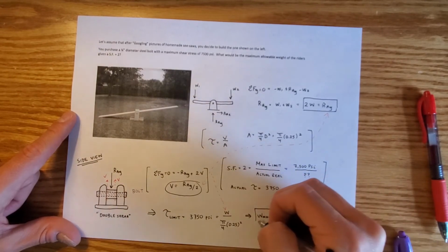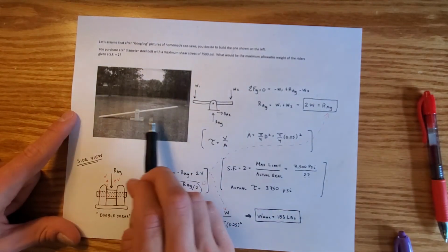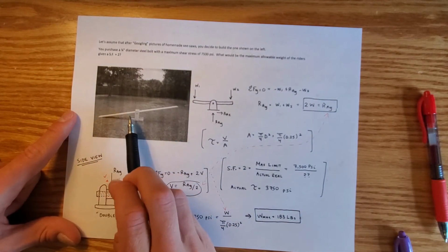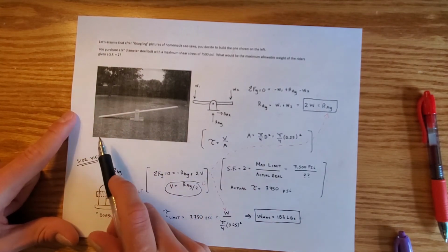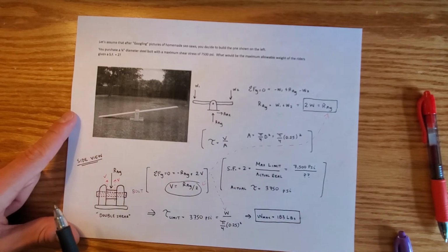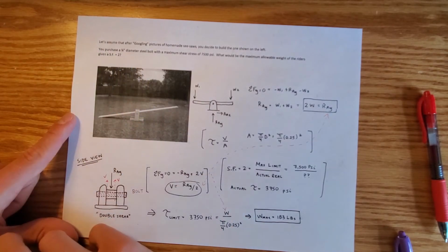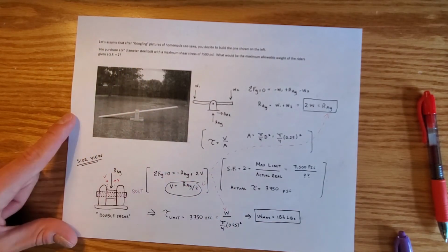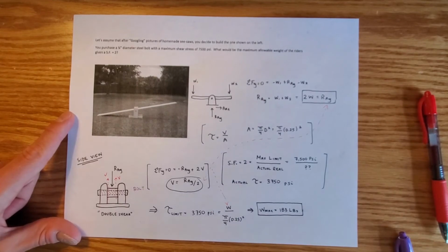So the seesaw is definitely strong enough to hold some little kids, but if you had a couple adults on here, the bolt would actually split in half, which is pretty crazy to think about, that you could split a 1/4 inch bolt in half, but that's the answer we get. And there you go. Be safe. Try and choose a bigger than 1/4 inch steel bolt if you're going to have a couple of hooligans playing around on your seesaw. But that's how you apply all the stuff you're learning in this class to something in the real world that you actually could build yourself.